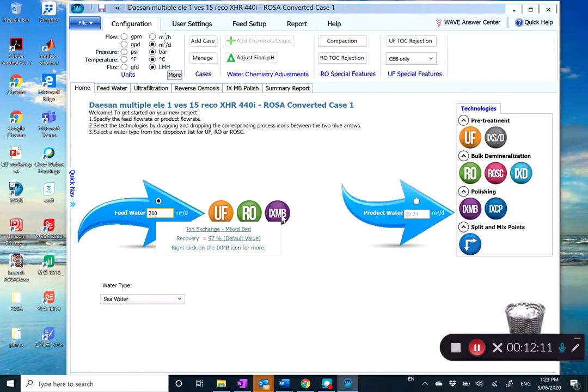And for the ion exchange, RO permeate still has around 300 milligram per liter, or less than 100 milligram per liter. However, when you utilize your RO permeate for the cooling tower or very ultra pure water, you need to go through ion exchange resin to remove most of the salt, sodium and chloride.